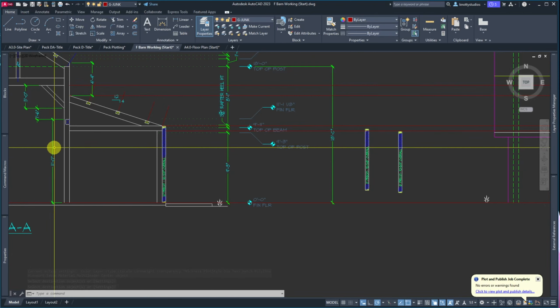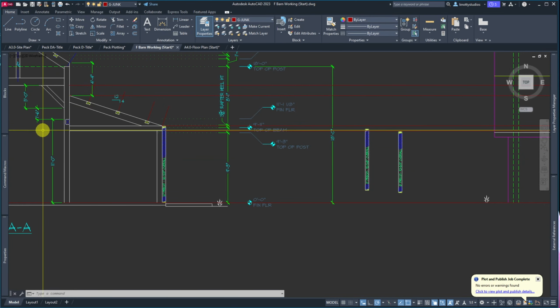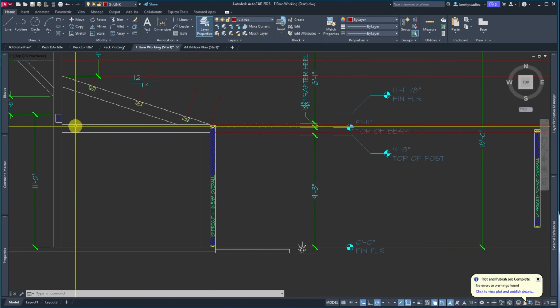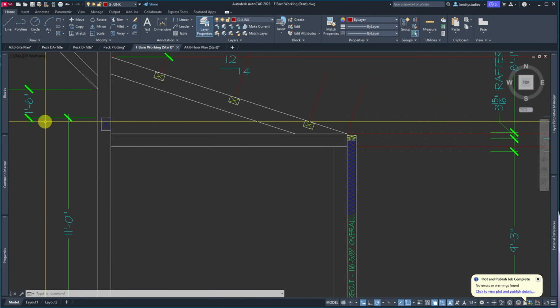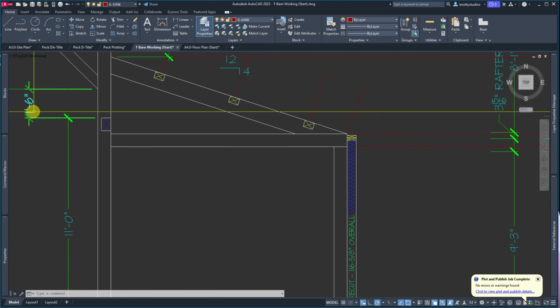So that's where I think the 11 feet, I think the dimension he has in there is incorrect. I think he drew what he wanted, but he accidentally dimensioned it incorrectly. So it'll be 6 inches higher than what he's got shown here. Now I bring it to, no, 8 inches higher.